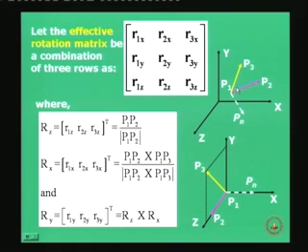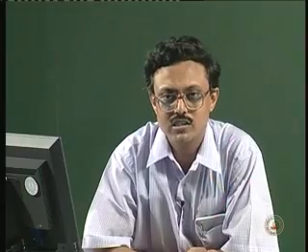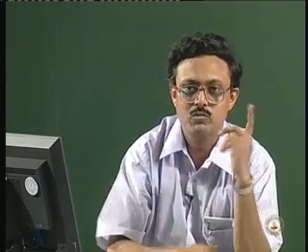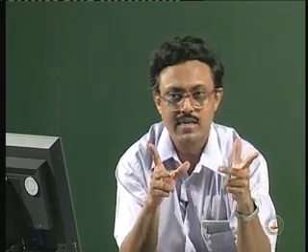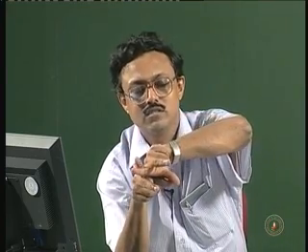That will give you the vector which will align automatically with the y axis, because after you have aligned P1 P2 with z and P1 Pn with x, automatically the cross product of these two will get aligned with the y axis respectively. So, the cross product of Rz and Rx will be the elements of the y axis. So, this is the philosophy or concept by which you come up with an effective rotation matrix by which any arbitrary 3-dimensional coordinate system can get aligned with another coordinate system respectively.